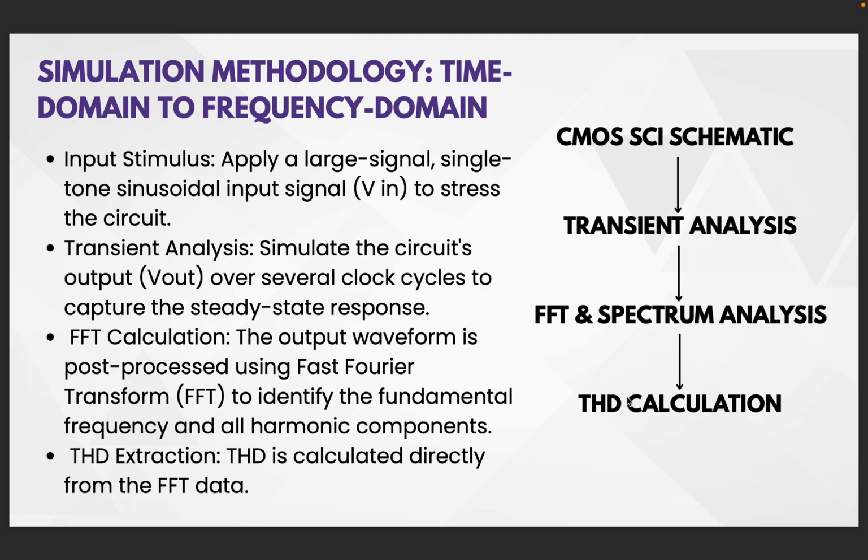Simulation methodology, time domain to frequency domain. For the simulation methodology, we started by applying a large signal single tone sinusoidal input to our CMOS switched capacitor integrator. This helps test how the circuit behaves under real working conditions.